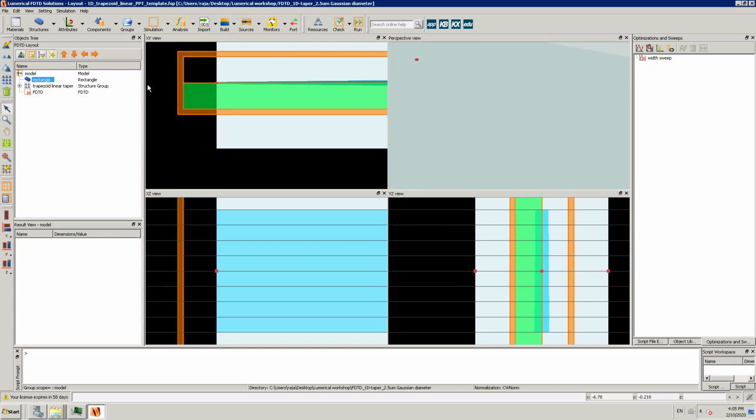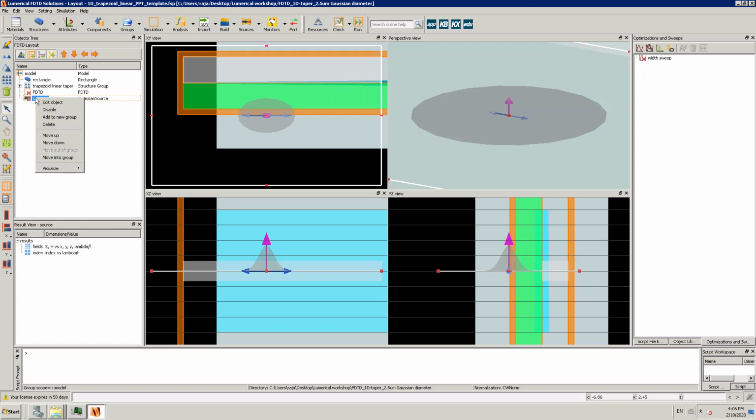Okay. Now we have to put the source. So first we put our waveguide structure, then the simulation region. Now we have to put our source. As I mentioned, it's very difficult to design a lens fiber. We know from the manufacturer that the mode field diameter of this lens fiber is 2.5 micron. So we can just pick one Gaussian source, and set the mode field diameter around 2.5 micron as our source. If we go to the source section, there's an option with the Gaussian. Now we can edit this.